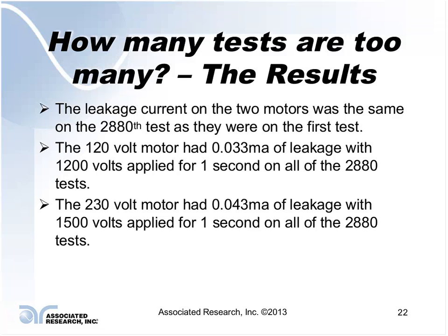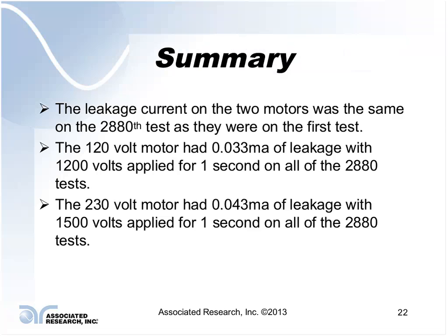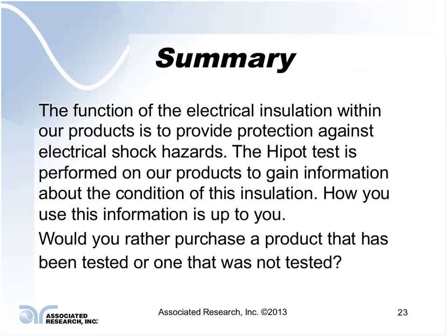Some standards will tell you to reduce the test potential based upon the altitude at which you're testing. Keep in mind, the function of the electrical insulation within the product is to protect against electrical shock hazards.